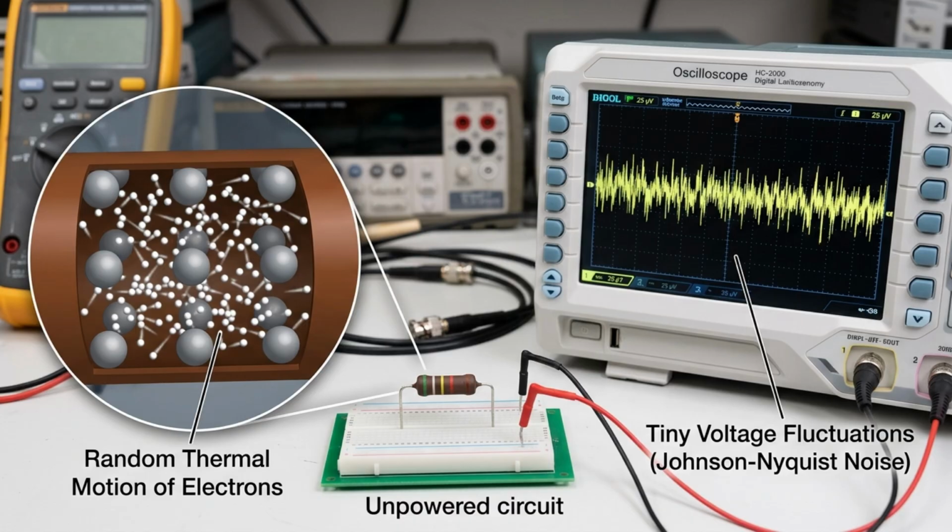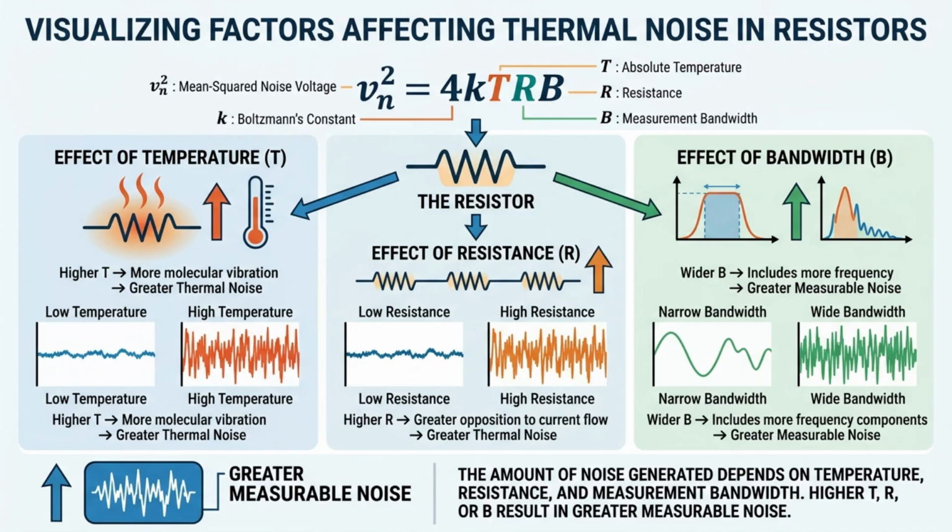The noise is completely random and cannot be eliminated unless the resistor is cooled to absolute zero. The amount of noise generated depends on the resistor's temperature, its resistance, and the measurement bandwidth. Higher temperatures or wider bandwidths result in greater measurable noise.